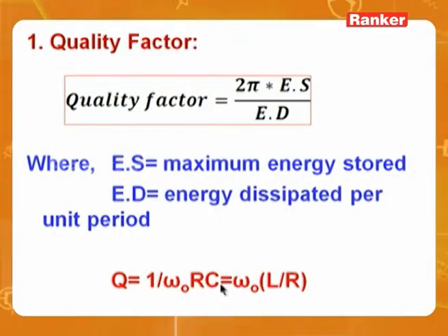We have seen in resonance the rise time was a very important factor. Here quality factor is very important. The whole world is stuck on one question: how to increase the quality factor. If you want to increase the quality factor, the best thing is to make an ideal inductor. That's the meaning. So the quality factor after calculating becomes 1 by omega C R, or omega L by R. In general, you can simply say X by R. This equation is finalized as reactance by resistance. Okay, let us use this quality factor in our further discussions.